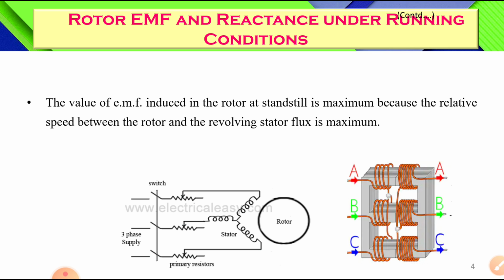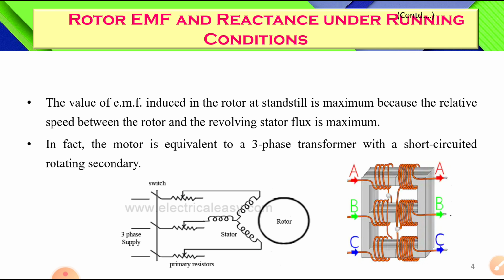In fact, the motor is equivalent to a 3-phase short circuited secondary. Just like the secondary, the rotor is in short circuited condition, whereas in the case of the slip ring induction motor it is also shorted with the external resistance. We have seen all these things.